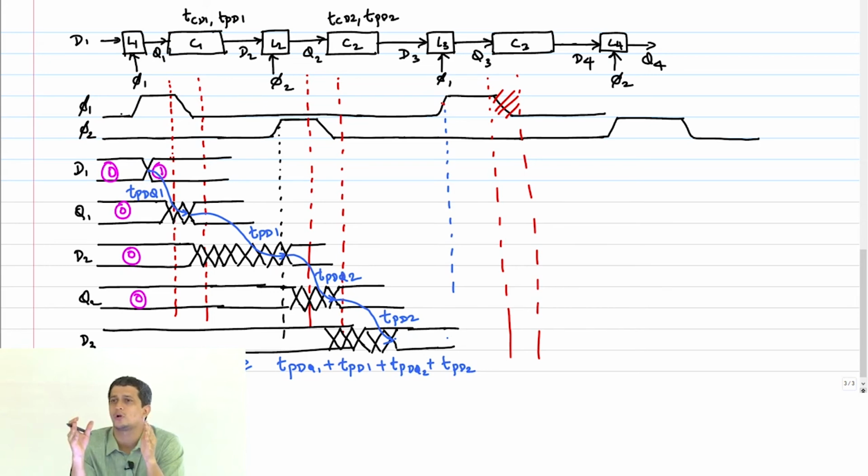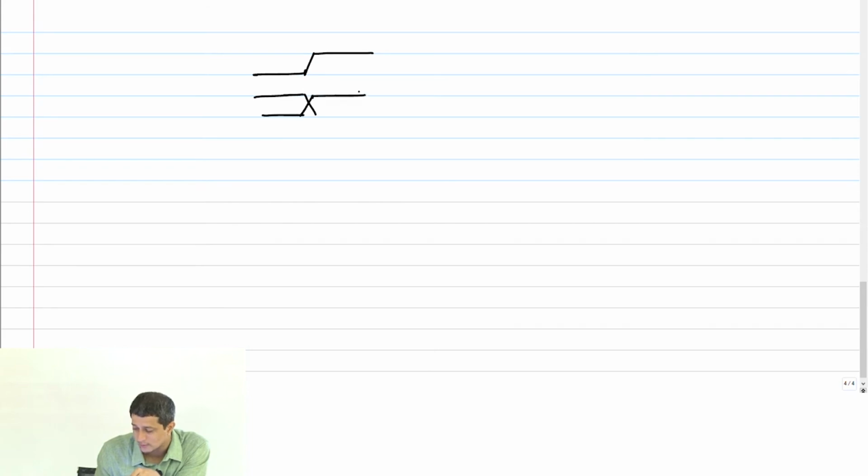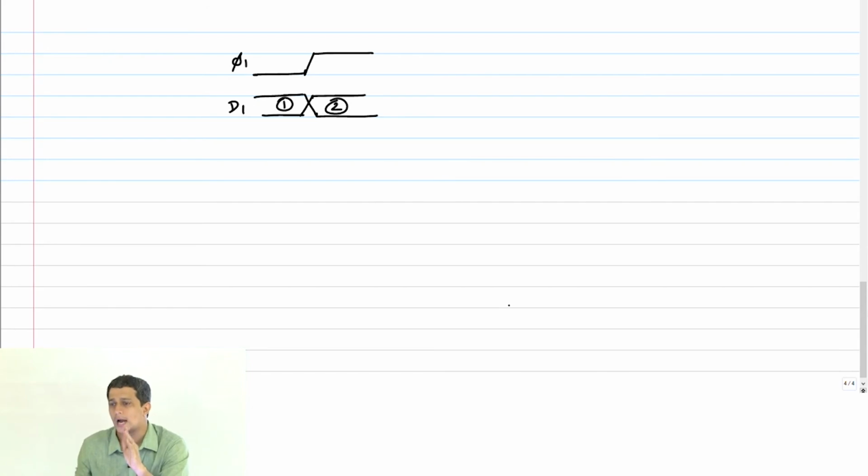No, no, that's what I'm saying, because the latch is becoming transparent after that. Let's assume the change in a latch, my clock is here, and the data changed exactly here. This one is D1, this is D2. Event 1, event 2. What is the aim? Ultimately, when the clock falls, which data should the latch hold? Event 2. That will happen, right?